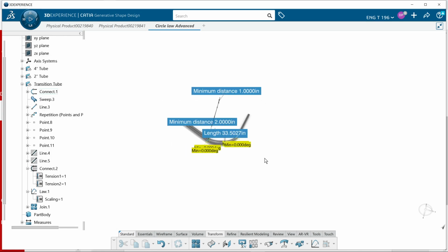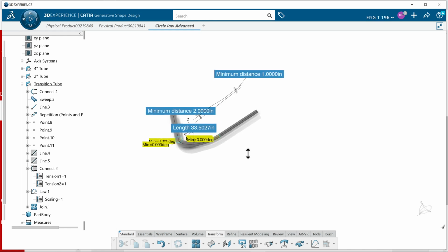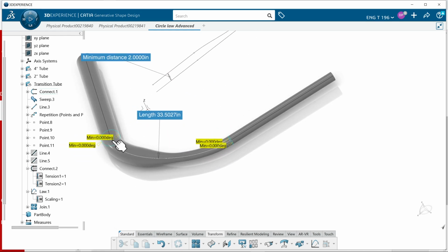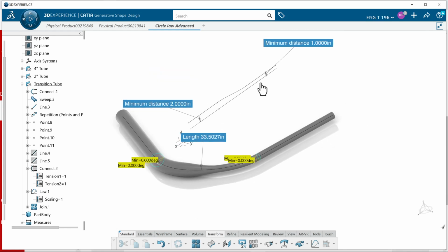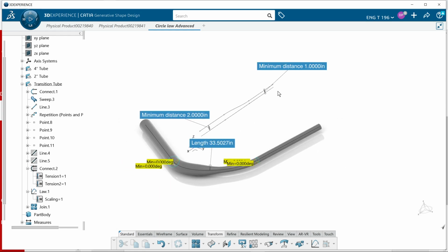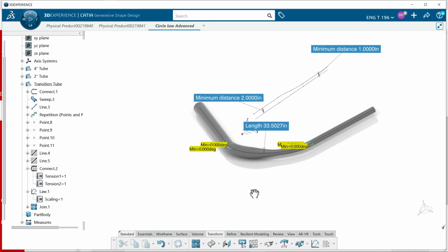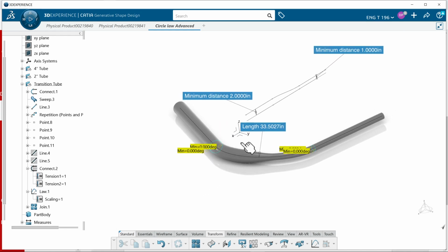And so the reason why I create my definition curve the same length as my connect curve or my spine for this center is, for me, it's easier to calculate a third over and a third over and just the ratio from one to the next. It really doesn't have to be that way. You could have made it 30 inches long and went 10 inches and 10 inches and I'd get the same result, okay? But I like to have my reference definition, my reference curve, and my center spline for this tube to be all the same.